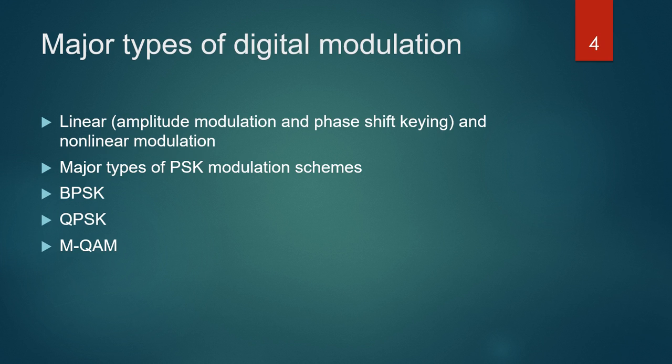The corruption of data could be attributed to many possible factors, including the modeling of the channel, which might change with time, the attenuation of the signal that may be caused due to the properties of the antenna, thermal noise, intermodulation noise, and channel fading, which may be caused due to destructive interference. These factors of noise will reduce the quality of the signal at the receiver, making it very difficult to comprehend the received signal, which will lead to erroneous decoding of the data.